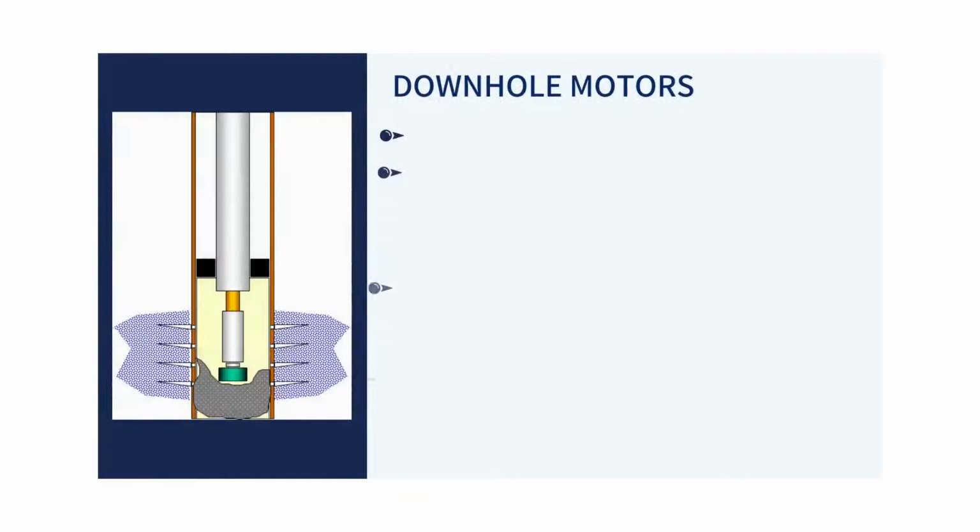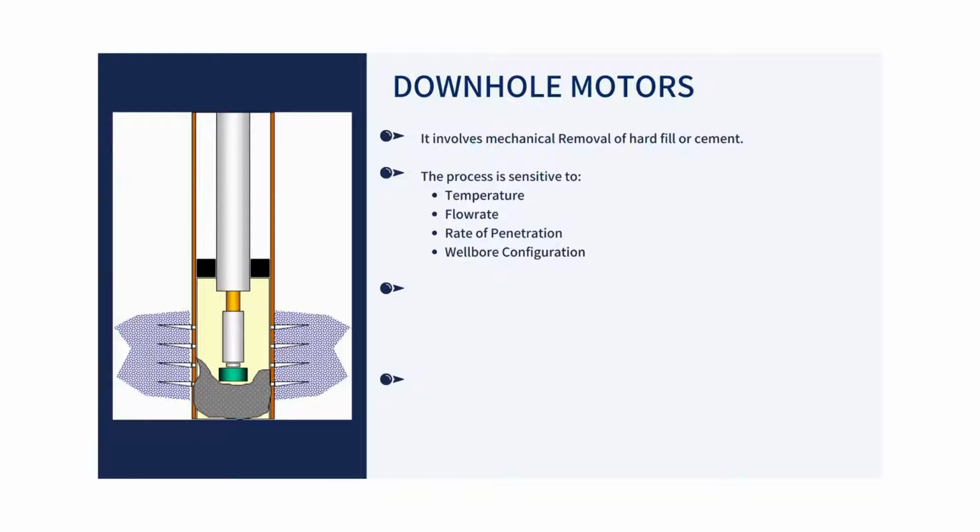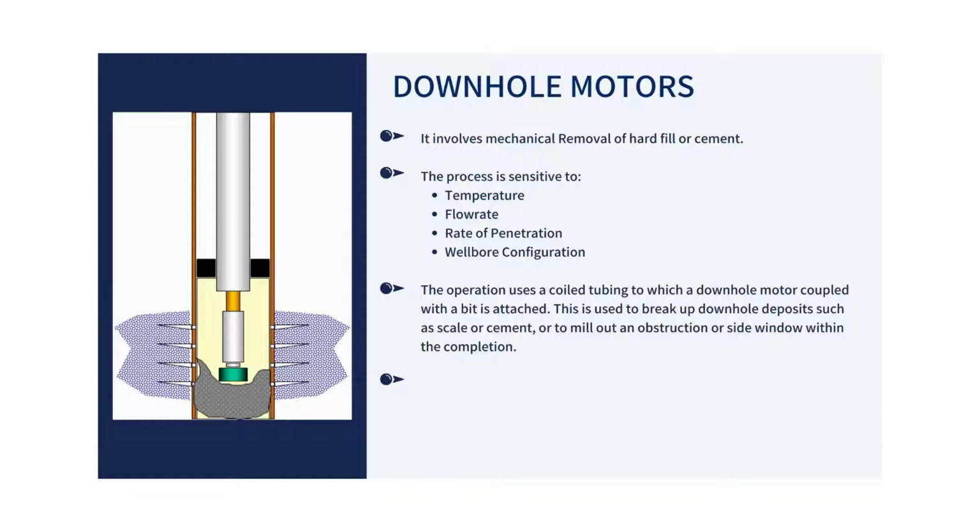Next, we shall understand downhole motors. It involves mechanical removal of hard fill or cement. The process is sensitive to temperature, flow rate, rate of penetration, and wellbore configuration. The operation uses a coiled tubing to which a downhole motor coupled with a bit is attached.